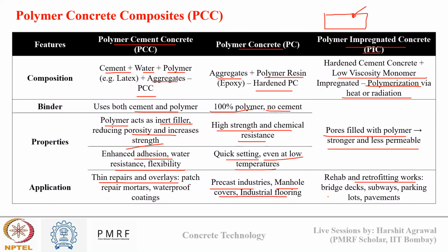So if we see cracking in a bridge deck, in a parking lot or in pavements, we impregnate the concrete crack through polymer injection to fill the voids and to reduce the transport of water or leakage in those structures.